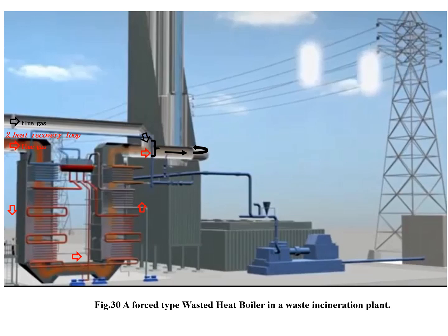The picture shows the heat is recovered from the flue gas to produce steam before it is discharged to the environment through the stack. Furthermore, a bypass loop is installed to allow for continuous operation of the system while the waste heat boiler is undergoing maintenance.